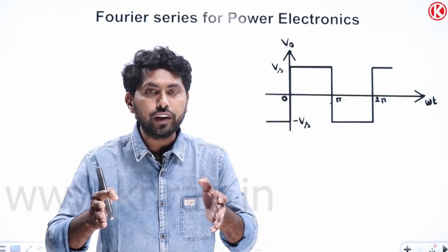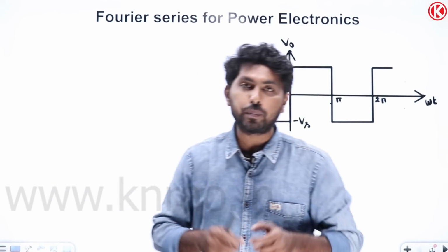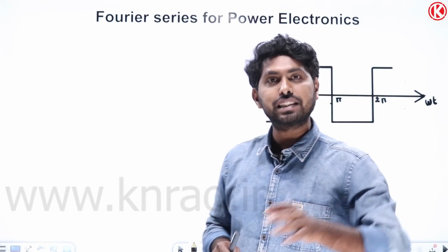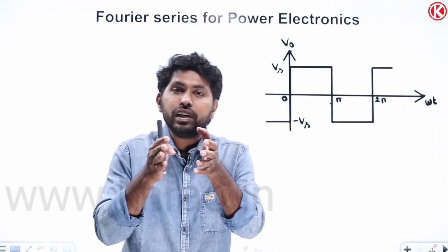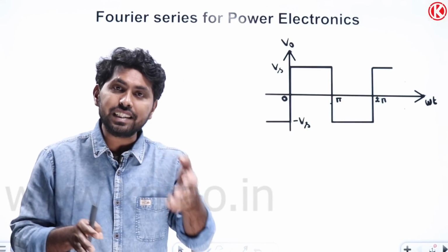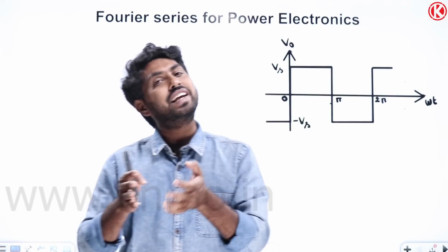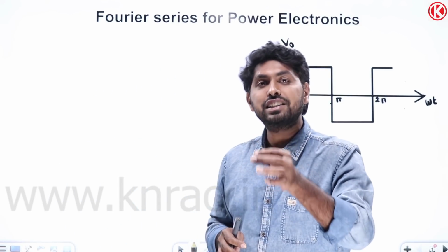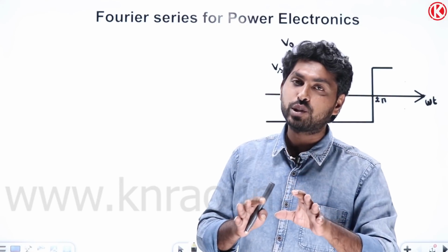So in this session we are going to discuss Fourier series for power electronics. Before going into the topic, why are we studying the Fourier series here? Because the Fourier series is a tool which analyzes the voltage and current waveforms of the rectifiers as well as the inverters. And the Fourier series is also a tool to analyze the total harmonic distortion.